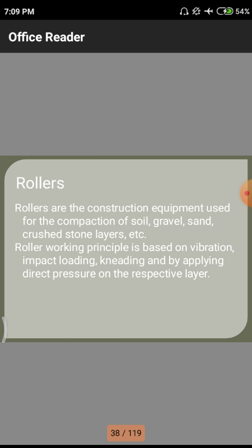That means in the rock industries, after the grinding of heavy amounts of rock, we are having some amount of stone dust and chips and others as waste materials. We have to use those waste materials by filling the below surfaces of the particular ground level. Next one we are having gravel. Gravel is used as a major content in road surfaces, so gravel is also compacted by using these rollers.